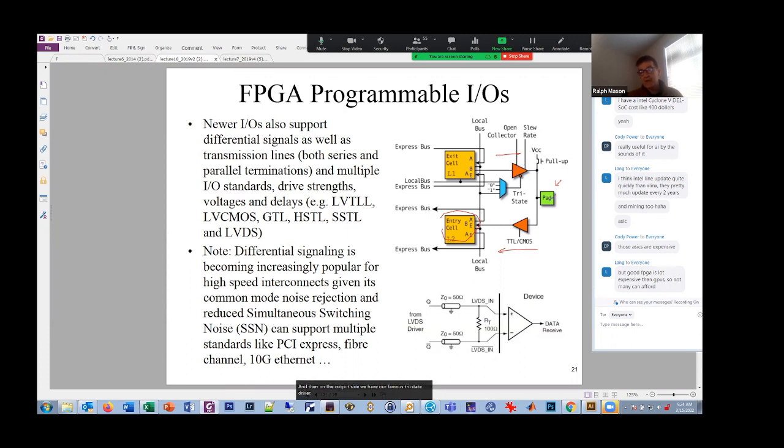So it can either drive the pad or it can be turned off, disabled. It has slew rate control that's for high speed. We might talk a bit about that. When you have transmission lines, sometimes you want to control the slew of it. The signal coming out can either be direct logic or it can have a flip-flop here to clock it. It has this pull-up. We learned about this before. Remember we talked about wired OR? So you can program that.